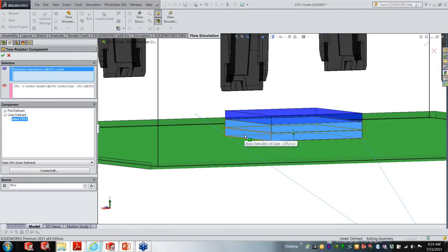And then our junction to board thermal resistance is actually modeled as an infinitely thin plate, or basically a contact resistance between the board and our junction here. So that takes a lot of complicated physics into account pretty easily for us. At that point, we can go ahead and define our heat source, so our load of 75 watts in this case. And when we run our analysis, what we're going to be looking for is the actual temperature of our junction body in this case. And it should be pretty isothermal.